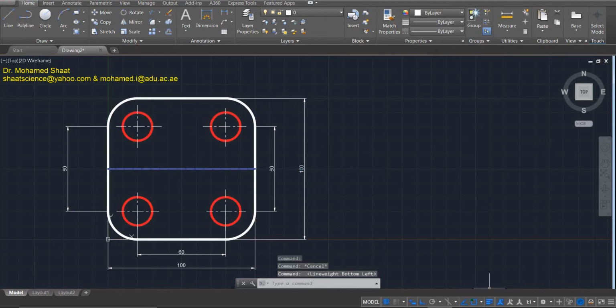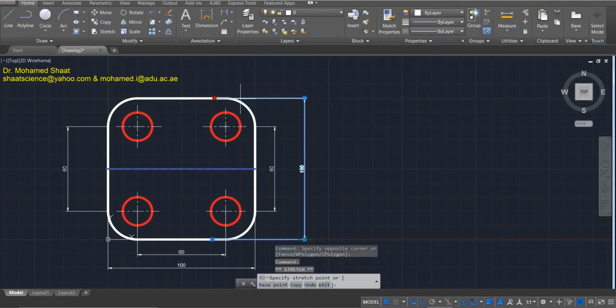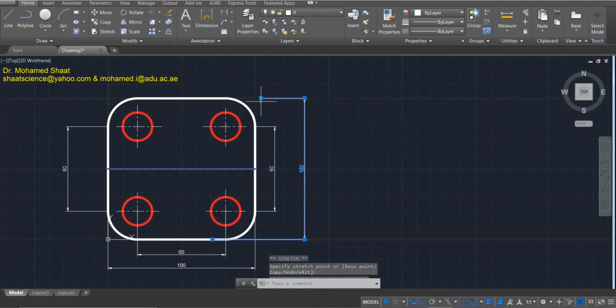If you choose the color, for example here, I just activated this one to see the contrast in the thickness. So as you can see, this thin line is the extension line of this dimension line, but it does intersect with the object, with the drawing itself, right? This is not acceptable according to the ISO standard. According to the standard, this dimension line, this point, should be at a certain space away from the drawing, so you aren't going to mix it up with the drawing.